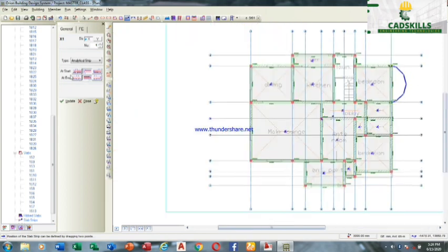I've set it up before coming here, and I click it. Now as I click it, this is at start, at end. This one means that it is cantilevered, beam is inside. This one means that beam is starting. This one means that it is also inside, it's cantilevering out with slab. This one means that beam is at the end. The same thing applies to this. So this is the pattern we are going to use because of what we have on ground. We're going to have beam starting and beam ending.